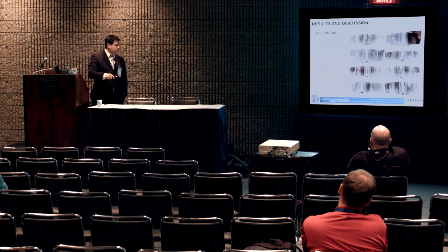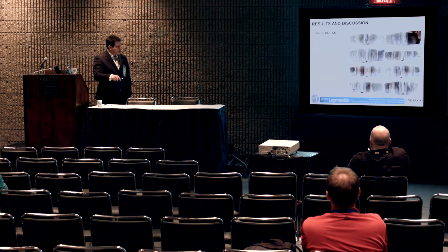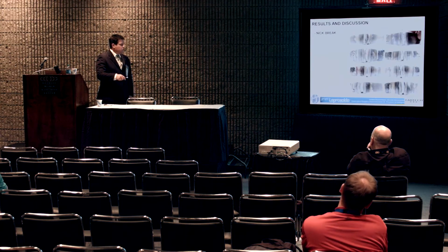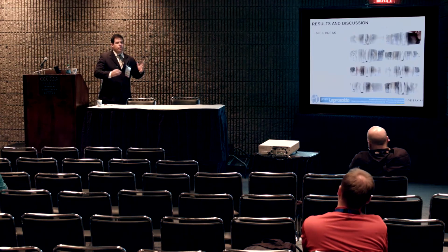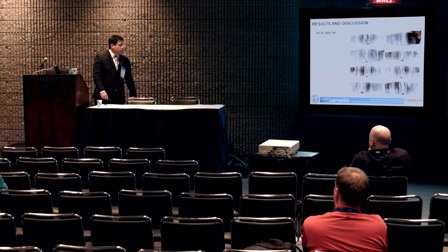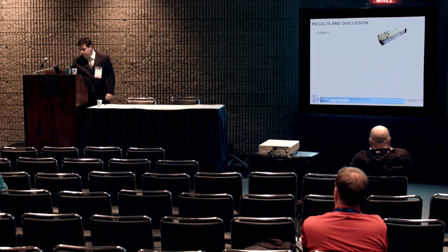Nick break, because even API 1104 says nick break. Once you have a mechanized process, you wouldn't have any problem. We did nick break testing, but we looked at the fracture and we got no pores, no slag inclusion, nothing like that. So nick break was just pro forma. Nothing new came out of that.